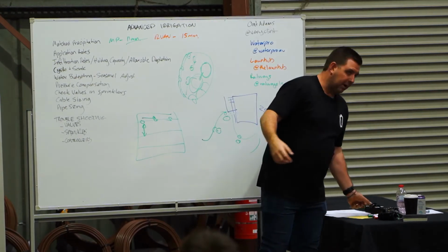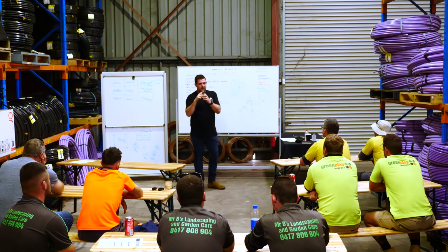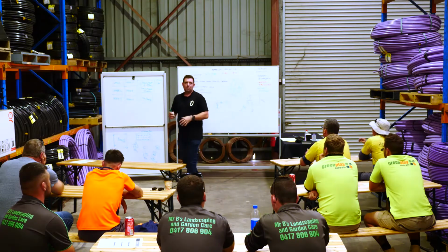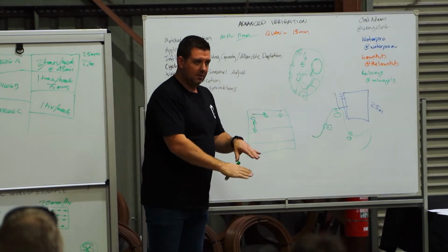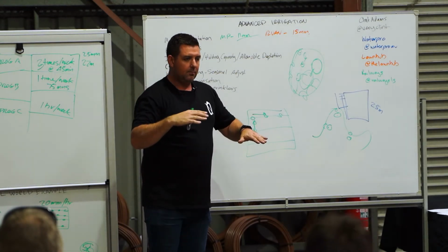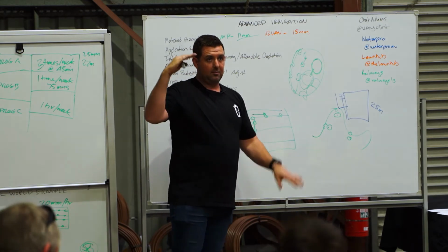So the sprinkler itself has the thing pop up. In that shaft, it has a pressure regulator, which is micro pressure regulating the whole system. So if you think about, you might have a terraced lawn where it's 2 meters difference. That 2 meters is affected by gravity. So 2 meters further down is delivering 20 kPa more pressure to the sprinklers than the sprinklers above it.